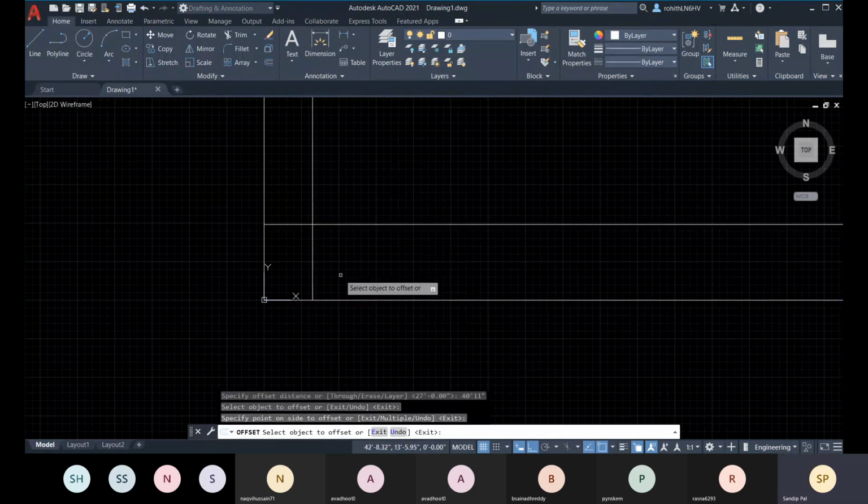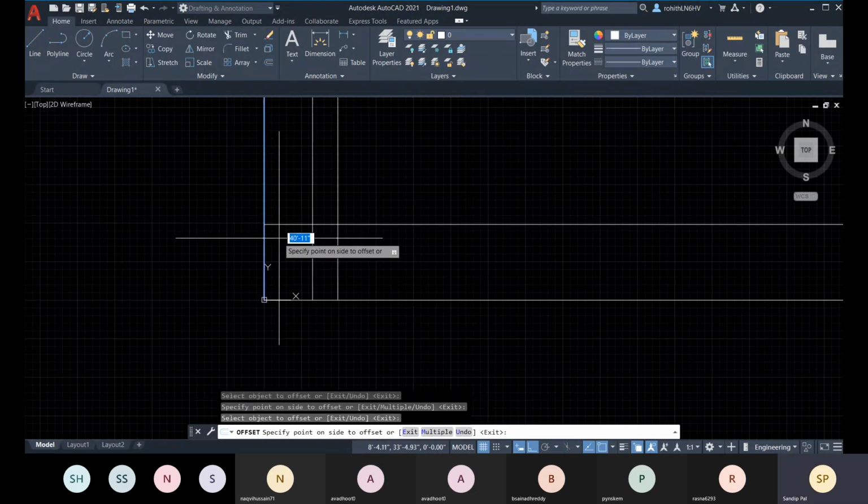Okay, and about your wall thickness, that is also provided. 10 inches are the outside wall thickness and 5 inches are the inside wall thickness. So let's go for it. Let me select, and here that is going to be 10 inches. So your default unit is inches. Now, if you don't press the symbol, it will take it as inches.